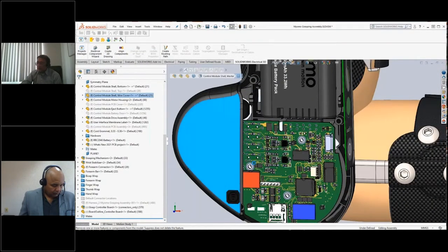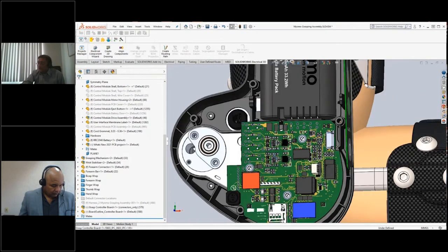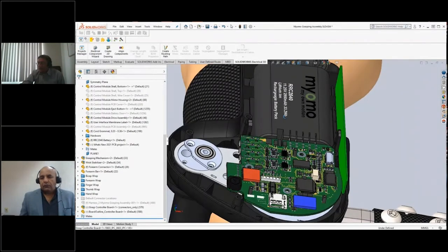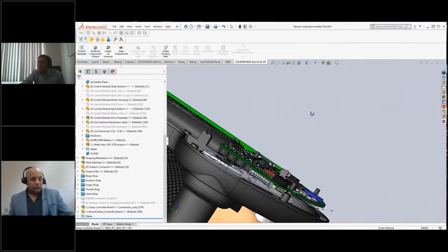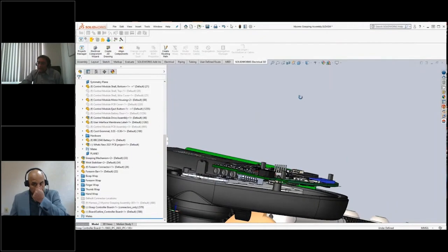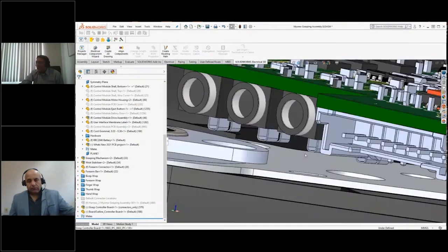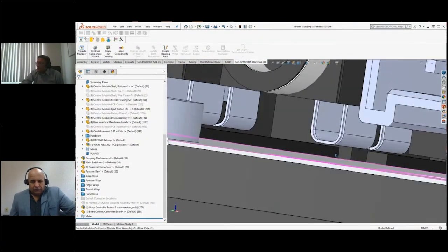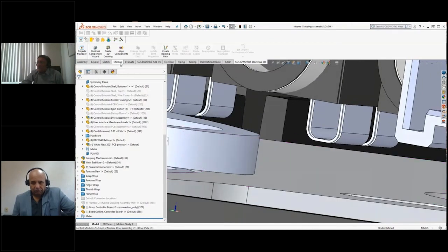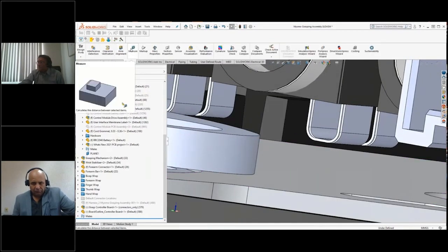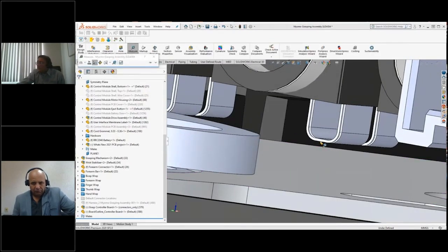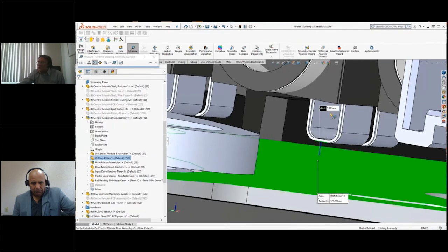If we open the second compartment, we will see that the shape of the PCB is not rectangular. It's a strange kind of shape. It has to fit according to the mechanical design. So the challenge is that mechanical engineers are going to design their system, and now you need clearance, front and back side. For example, if you measure here, this backside connector to that metal plate down, it is about 0.5 millimeter, right? That's the high precision that you need.